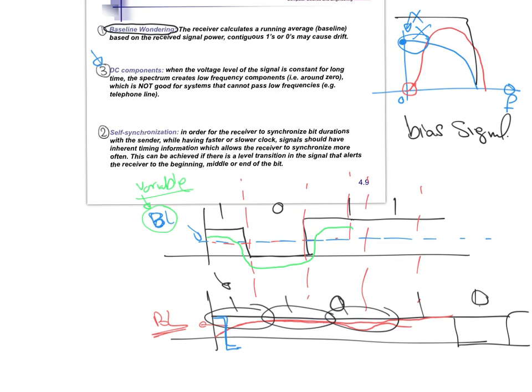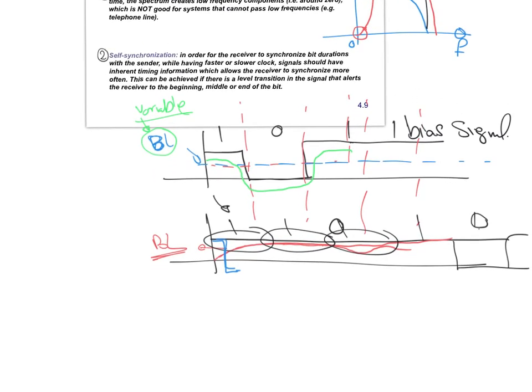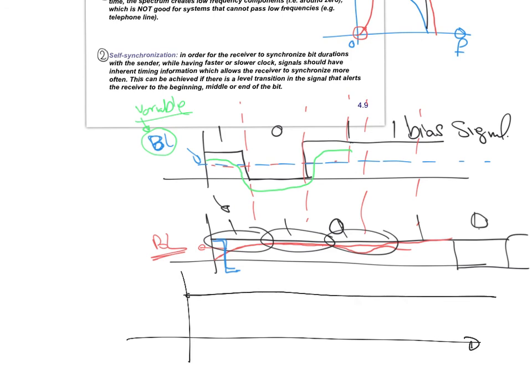So, when do we have a DC component? If we have a digital signal that has positive voltage, the same fixed level of voltage for a long duration of time, what is the frequency of this signal? What is the frequency of this? 0. Right. What is the power? Because the voltage level is positive, the power is actually V square. Right? So this is what we call a DC component.